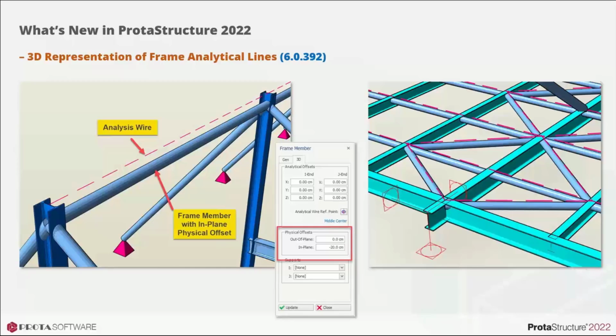So, in other words, engineers usually don't want to create an eccentric analysis model with lots of rigid links and lots of small frames and lots of nodes very close to each other. Engineers usually don't want to create a dirty analytical model just to model simple eccentricity.